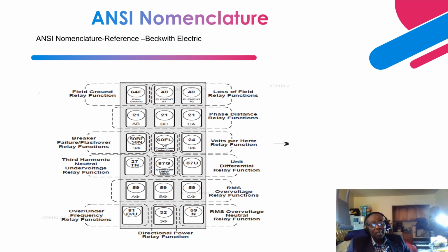And also, we have a frequency element in it. It's a V over F, so the V stands for voltage over frequency. For frequency, if you have a heavily loaded generator, you can have a drop in frequency in the AC grid, and that can affect the volts per hertz setting as well.